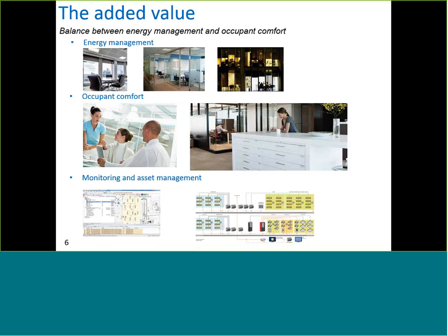This is also an area where we are able to introduce more features, as we can have the scheduling affect the timeout on those sensors. When motion sensors are set for after hours, they will have a very aggressive energy management strategy and only be set for 5 minutes, and therefore not constantly triggered by security and cleaning staff. But then during trading hours, we can extend that timeout by a network message instructing the sensors to have a 45-minute timeout, so they're not being disruptive to the occupants within the space.